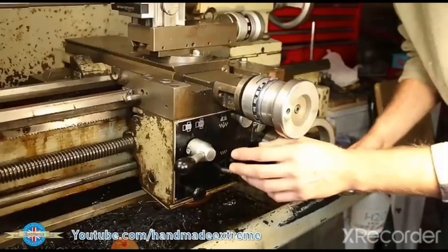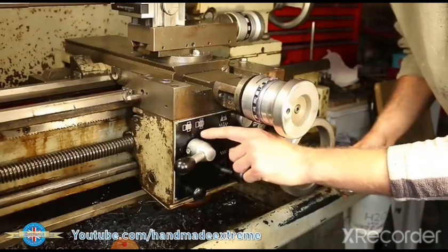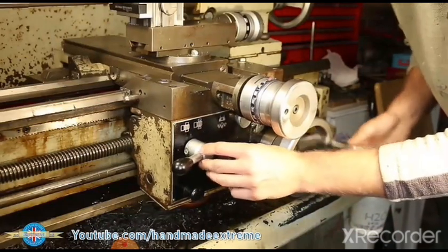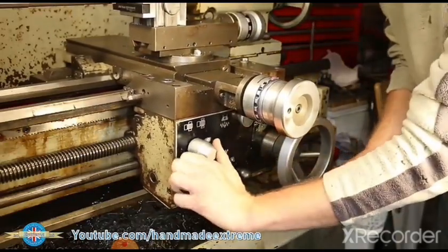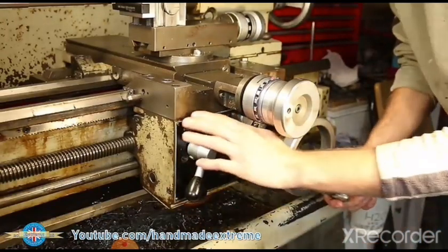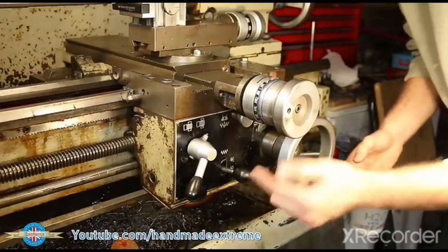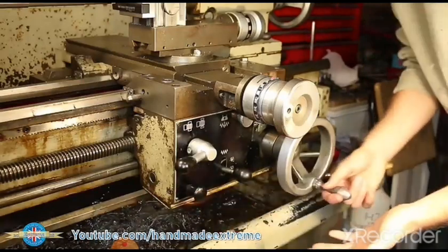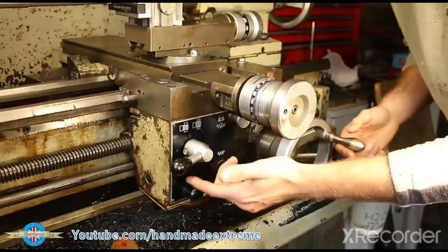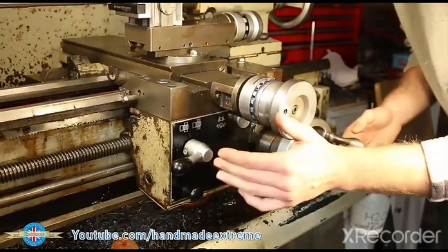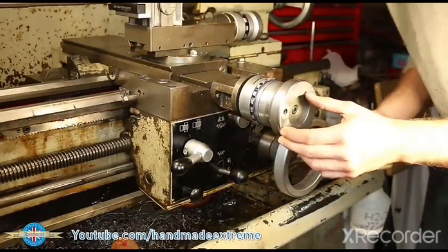To actually engage and disengage our threading tool, we're going to use this lever just here. This is the half nut engage and disengage. At the moment, I can move the saddle back and forwards freely, and if I engage the half nut, the saddle is locked onto the lead screw. So if the lead screw is spinning, that will drag the saddle backwards and forwards depending on which way the lead screw is going. Then we disengage it and we can move it freely again. This means that we can keep the machine running and disengage the half nut at the end of our thread and then just wind the tool back to the start. There's a little bit more to it than that, but we'll get into that in a second.